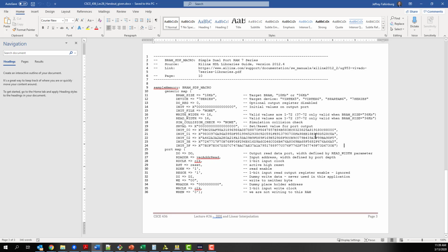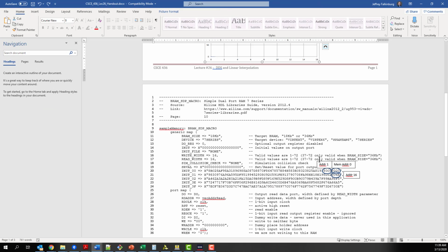And in the next classes, we're going to talk about how we generate a table like this. If you look at it, it reads from the right to the left. So you have memory address 0 on the right. And I'll show you. This memory address 0 is this 8000. So you have 4 nibbles, 2 bytes, 16 bits per memory address 0.